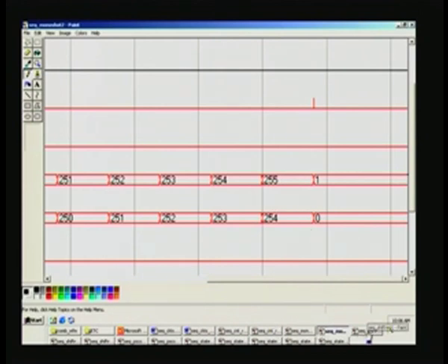Then we will move on to the shift register. But still that glitch is likely to be there, isn't it? Which one? No, that won't be there, because that signal itself will be removed. This signal is the result of ORing two things, right? Reset being active and counter being 255. We have clubbed them, that is why it is not a glitch as I mentioned. In the RTL coding guidelines we saw how glitches are found, it is because of differences in path delays. So now we will move on to the shift register.